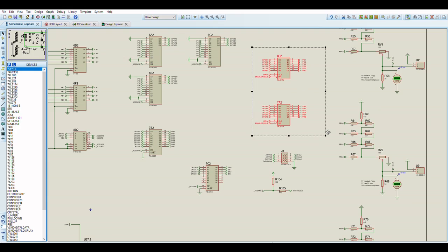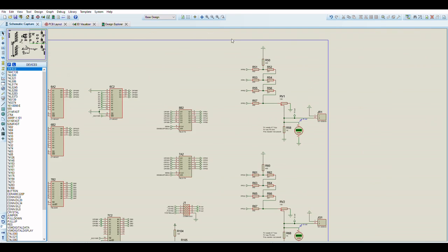These two do latch the internal pixel information from the palette information, so 4 bits of RGB in each. These are perfectly adequate for latching 12 bits. And they latch them for the outputs. And then these eventually go to the resistor ladders.